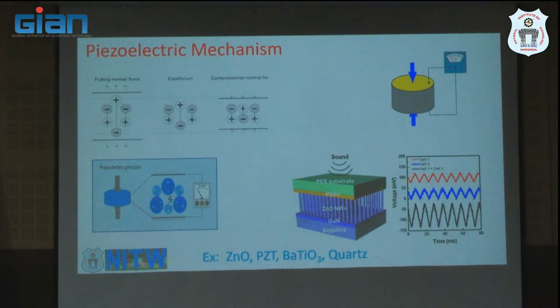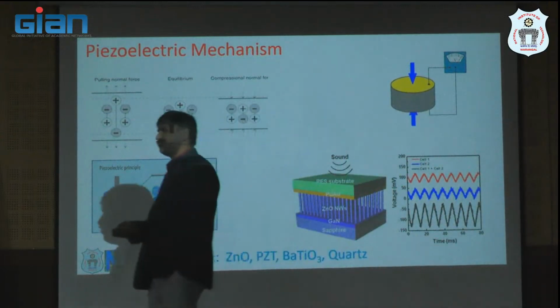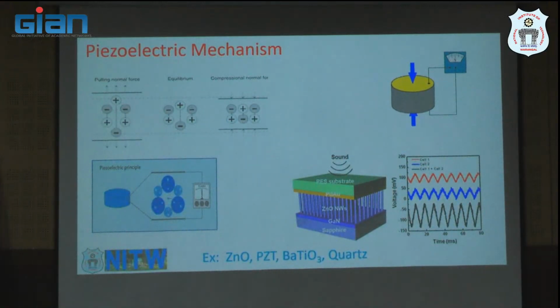So let's start with the simplest case. Piezoelectric, this you must have studied at school and college level, where there are certain kinds of materials, typically non-centrosymmetric crystals, where the centers of positive and negative charges do not coincide with each other. If you apply a pressure, the centers of positive and negative charge will not coincide. As a result, you are going to have a potential difference across the two surfaces. So the piezoelectric effect takes any mechanical energy applied on the substrate from the top side and produces the electrical output.